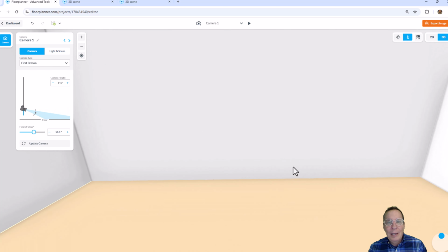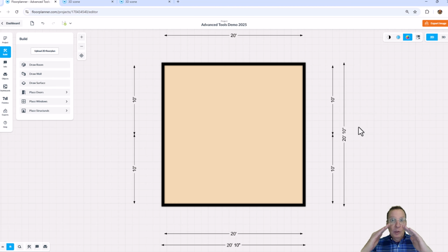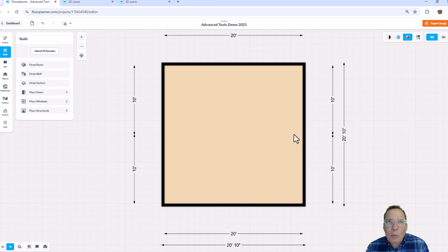Not too bad. Yet, if you're doing area, square foot calculations down here, because Floor Planner can calculate these spaces for you, you will not be able to connect them. So this could be an issue. May not work so well for you. Plus, if you had complicated architecture of other gables coming to this cathedral ceiling, a lot of 0 thickness walls could cause some grief or confusion. So I'm going to take that 0 thickness wall and I'm going to delete it, make it go away. 0 thickness wall is finished and gone, which means I messed up my ceiling again.